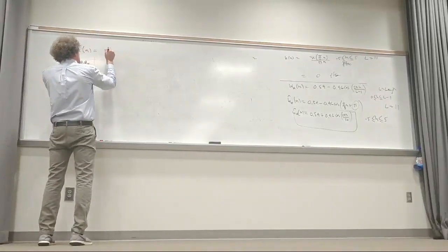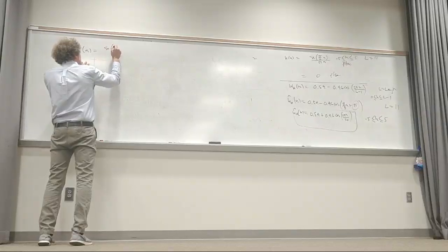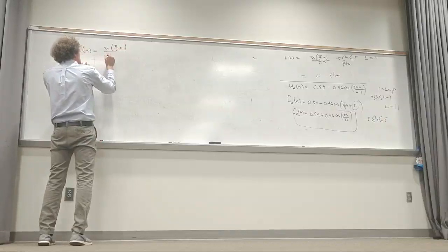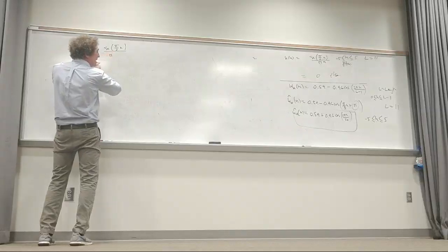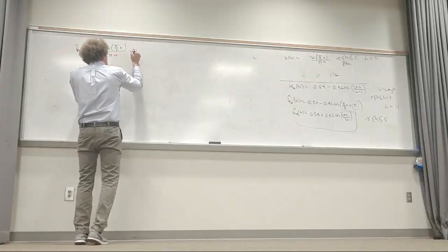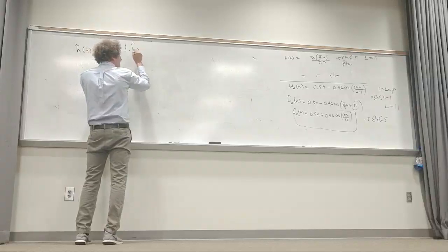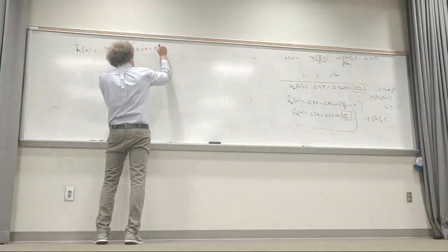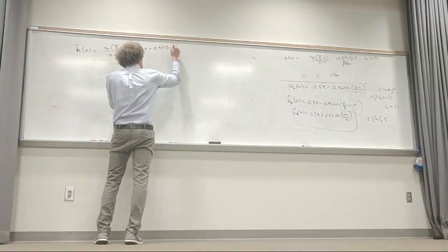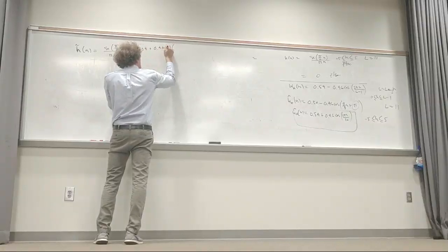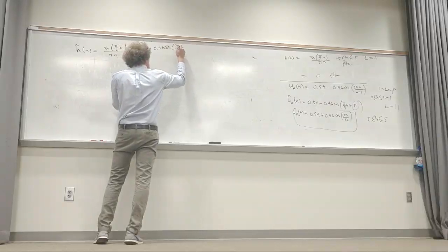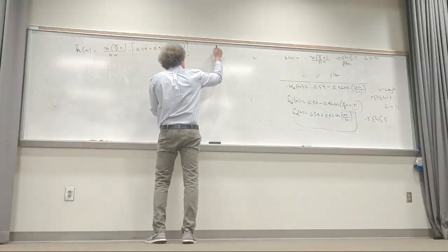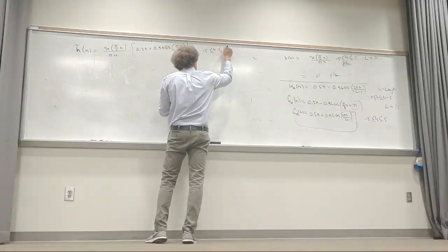It's going to be the sine of pi over 2 n, and then it's going to be divided by pi n, and it's multiplied by that window, which is then 0.54 plus 0.46 times the cosine of 2 pi n over 10. But this is still n greater than or equal to -5, less than or equal to 5.